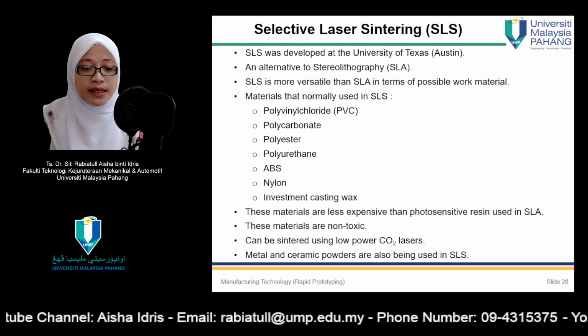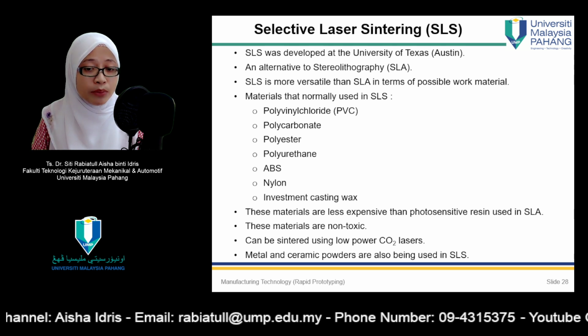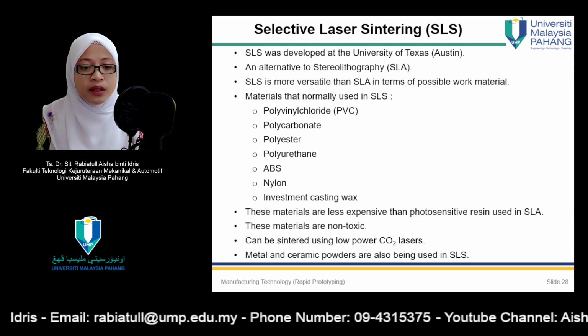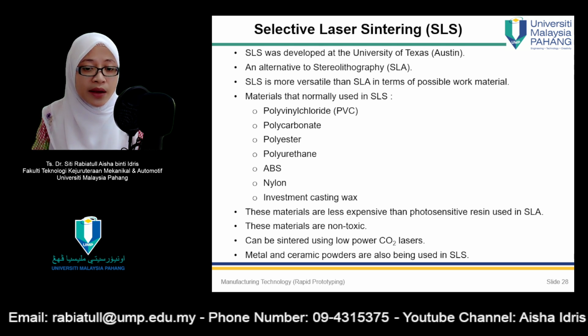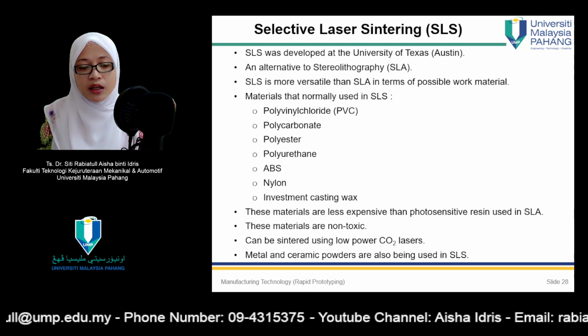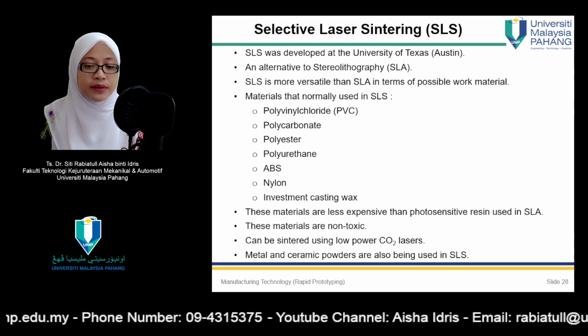In areas not sintered by the laser beam, the powders remain loose so they can be poured out of the completed part. Meanwhile, they serve to support the solid regions of the part during the fabrication process.